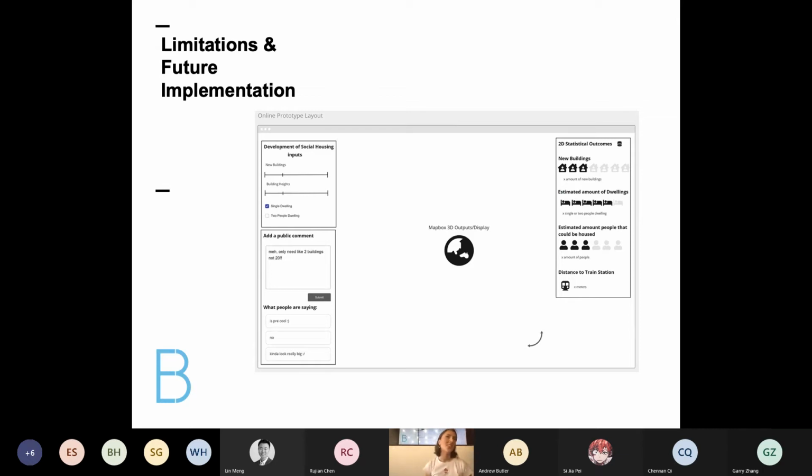Some unseen issues included messy data, and Urbano's transformation and metadata messed up a lot of portrayals in Grasshopper, which is super fun to work with. And GeoJSON issues including EPSG translation, which is like the origin point. When I was initially trying to get it into an online space, it was being projected in Russia, completely opposite side of the world from where I needed it to be.